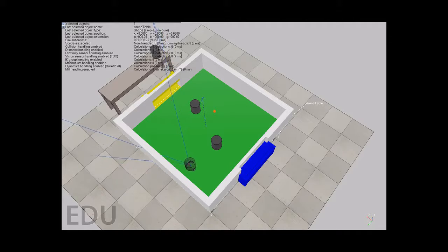To avoid obstacles, the potential fields method was used. Potential fields works by using the data from the vision system to calculate and sum the attractive forces of the goal object with the repulsive forces of the obstacles. This resultant force can then be used to calculate the velocity and angle the AI system needs to send to the drive system. With these forces constantly updating, it allows the robot to navigate constantly changing environments.